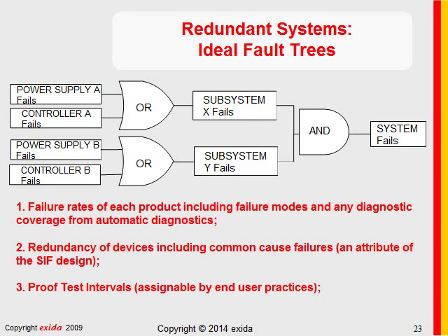And if we do that and use these simplified equations, and this is exactly what's done, for example, in Part 6, the informative portion of 61508, as illustrative examples. The problem with it, of course, is you have to be very careful about doing averaging before the logic, because you get a very different answer than averaging after logic.